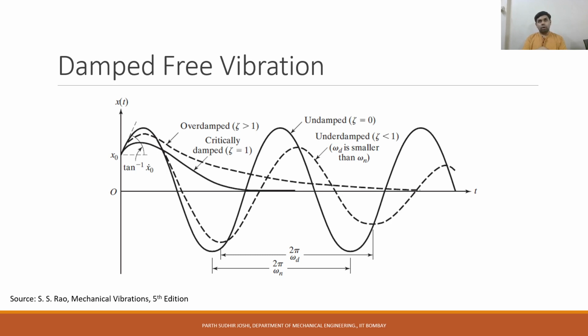So there, if we design it like an underdamped system, then the door will close, but it will show some oscillations. But we don't want any oscillations in that case. So there we can design it as a critically damped or overdamped system, so it will slowly close and decay slowly. You can relate that with the door example because you would have seen it in everyday life, I think.